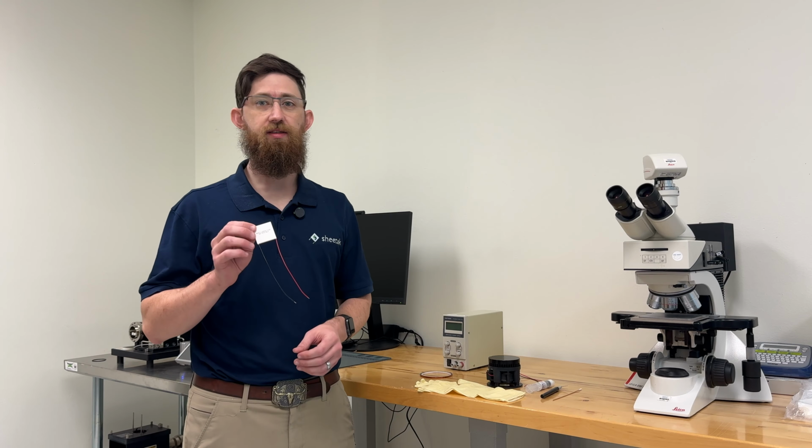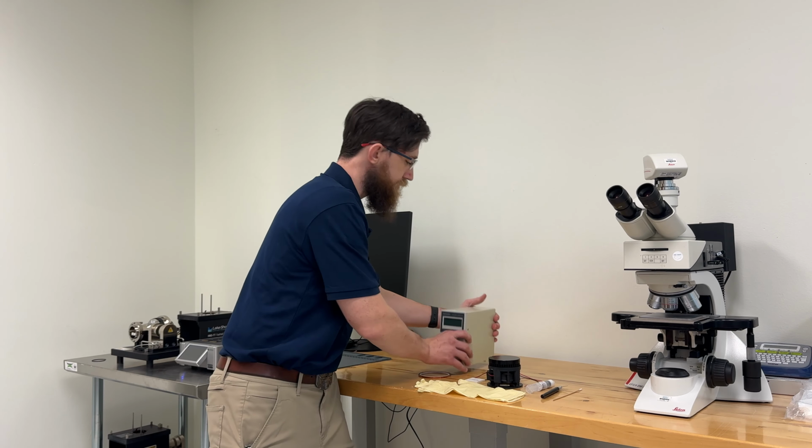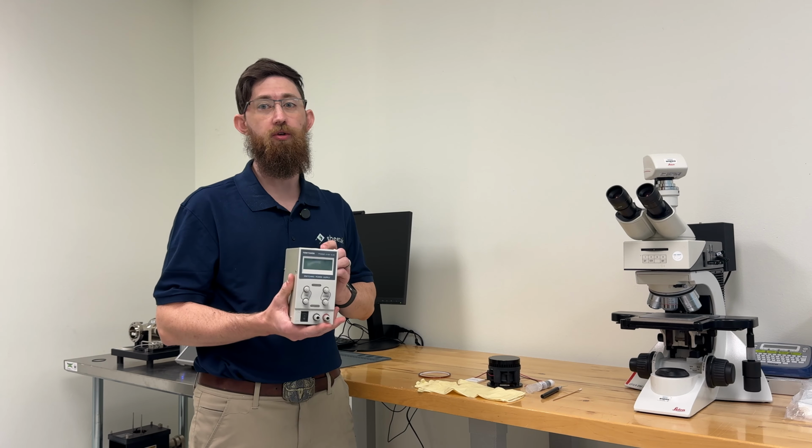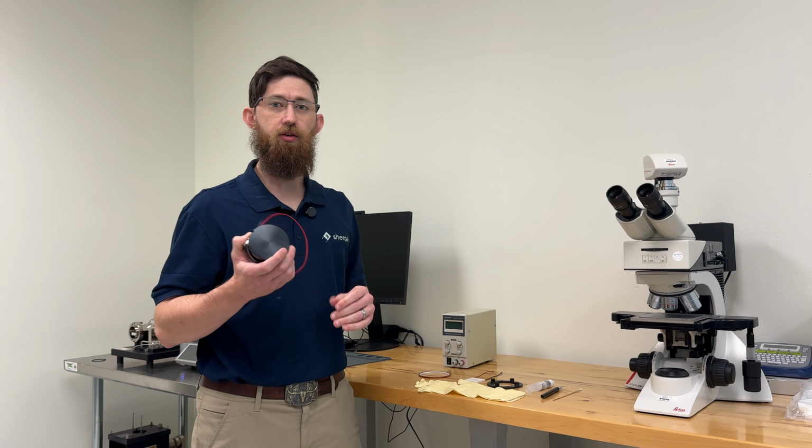In this video, we're going to walk you through how to design a basic TEC system, then we'll test our system by using it to freeze water. Today, we'll be using a TEC from our Centum product lines, specifically the 19908 model. And to show how simple TECs are, we'll drive it with the most basic power supply we have, and we'll cool it with an aluminum heatsink and a standard 12-volt fan.